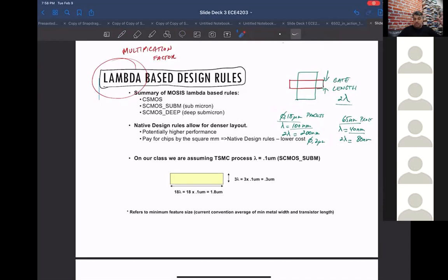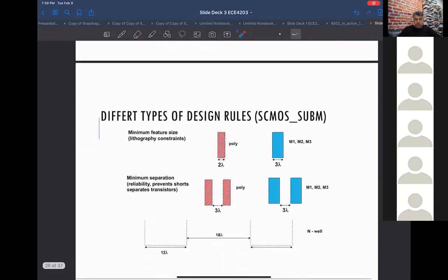It's just not as efficient. It's even worse here because although I have a 65 nanometer process, the shortest transistor length that I can draw is 80 nanometers. So again, I'm giving up a lot. This is something like 20% bigger than the minimum I could make. So it's not very efficient, but this is something people have done because we're in university, etc. So it's sort of popular.